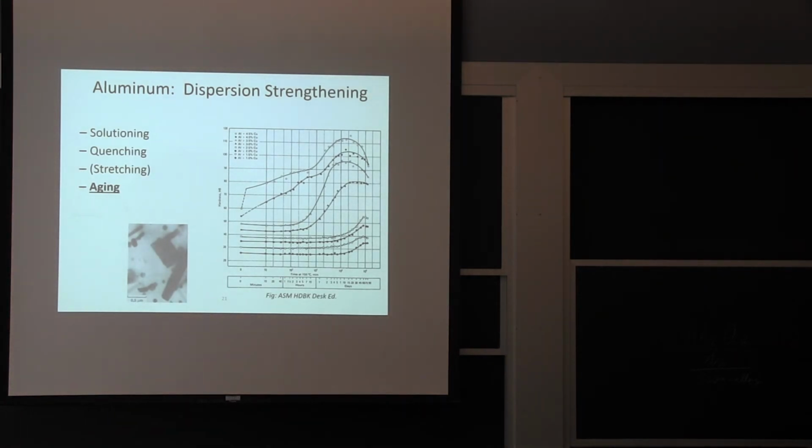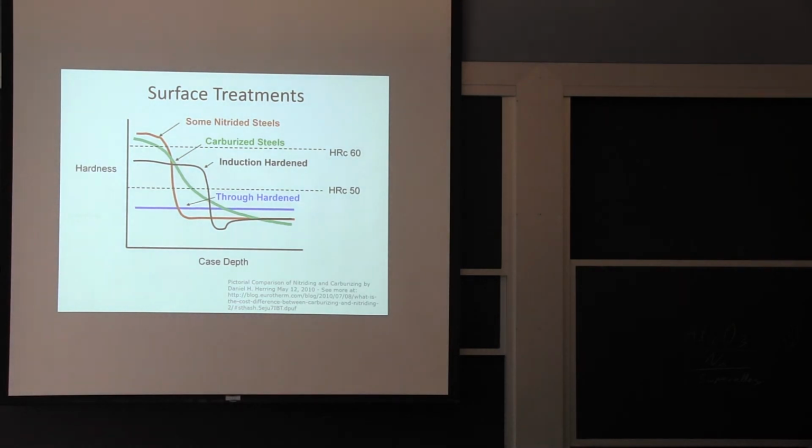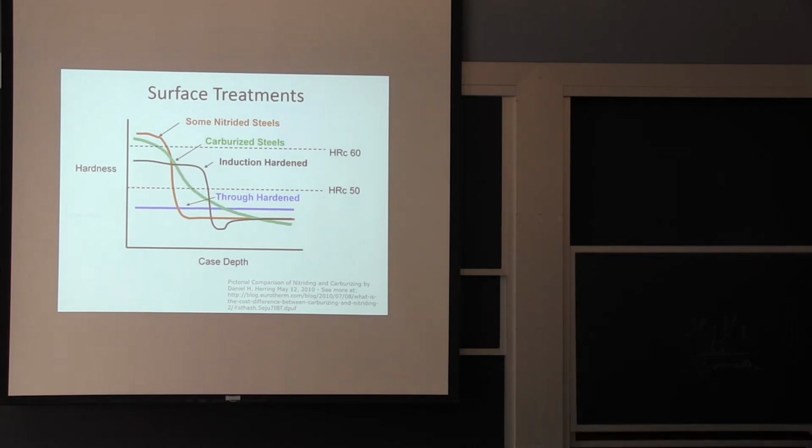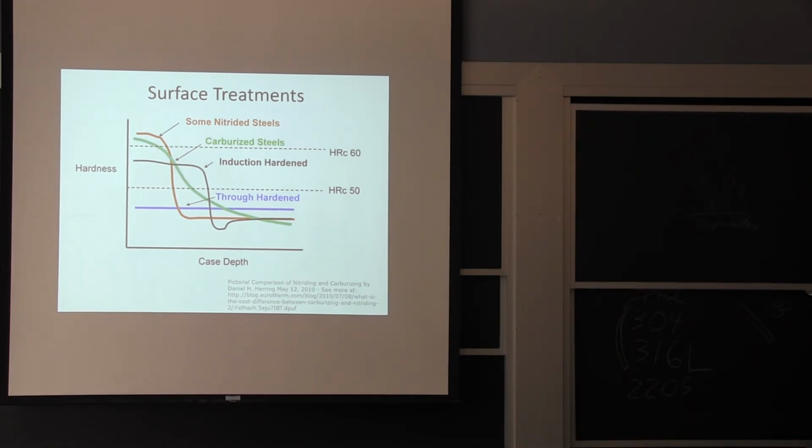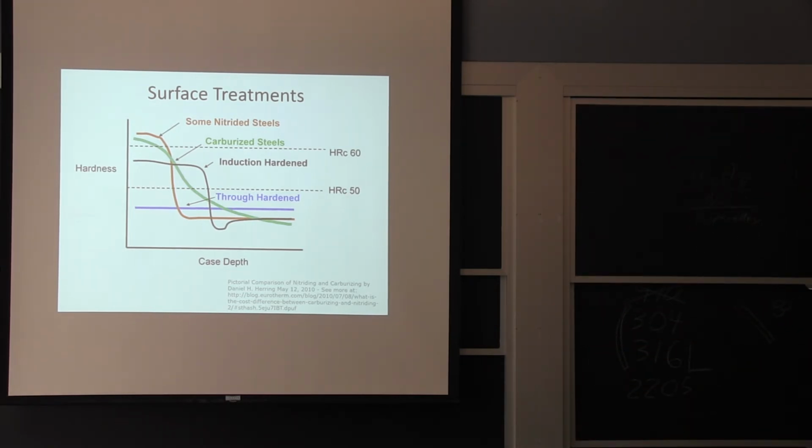The surface treatment is a topic I know I didn't cover everything. I wanted to talk to you about shot peening, for example, which is a process where you hammer the surface with beads or small particles, and that deforms them. So if I take the surface here, I'm sure you can understand. It's used a lot for aluminum. It's used for aircraft, helicopter blades.